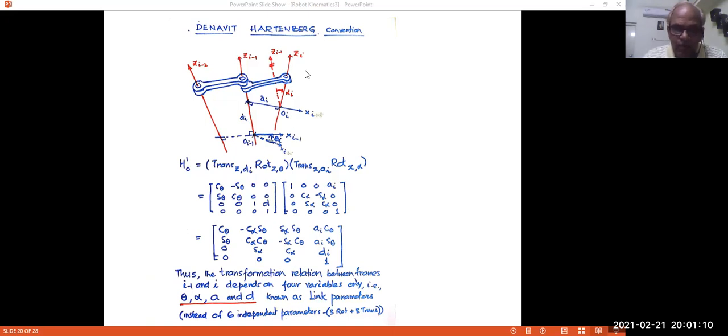Write the corresponding parameters for this link with the next link, and we call that H21 and write a corresponding HTM. We can then multiply all those, link after link, to obtain the necessary homogeneous transformation matrix.